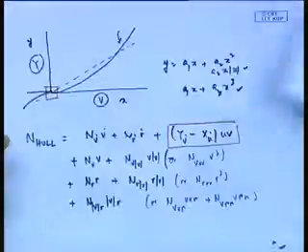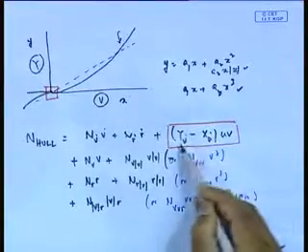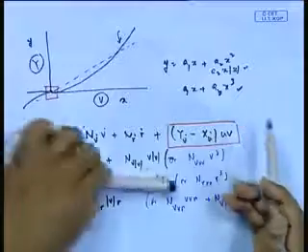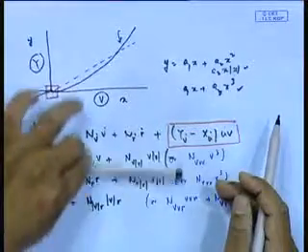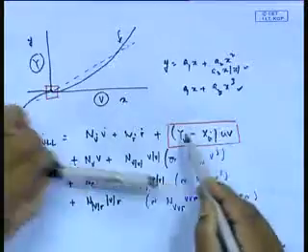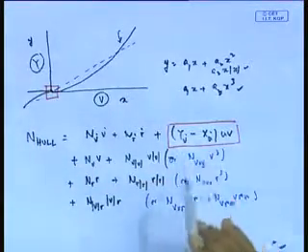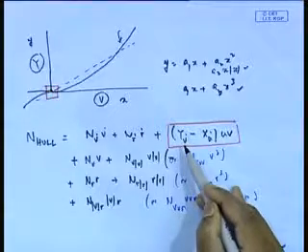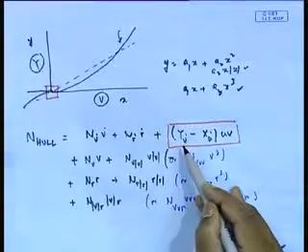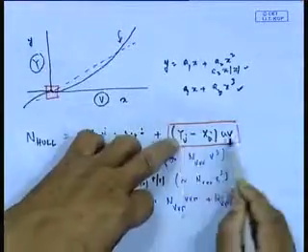Okay. But this one, Y v dot minus X v dot, is very small, but Y v dot is the added mass in this direction, because Y v is a very large value. So, this value becomes very large, this Y v dot u v, and Y v dot is always a large negative value, because Y v dot is the minus of the sway added mass. So, this is a negative value.